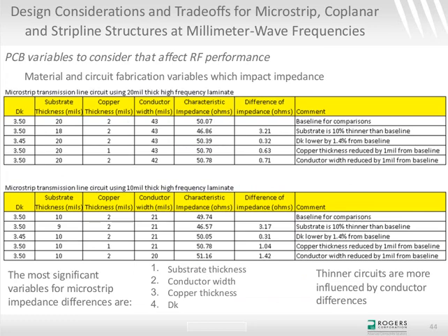So some printed circuit board fabrication issues. These charts, both these tables of information, are something really interesting, I think, because I've had customers come to me before and say, you know, we have this controlled impedance board, it's about 50 ohms, and we see this variation, and we want to use a tighter controlled material for dielectric constant. And actually, when you do the models, that's not what you really need that much. I mean, it would help, of course, but that's not the big thing. And anyone can actually take impedance modeling software and do this exact same model.